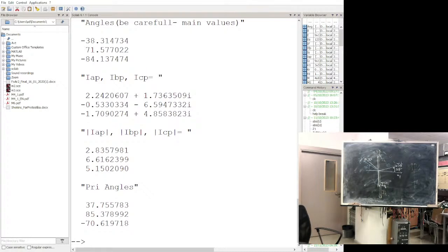Why? You see, the motor's current at A phase increases. Why? Because of this non-symmetry, in our theory, a negative sequence starts flowing through the motor. It's the addition that brings in the negative sequence.